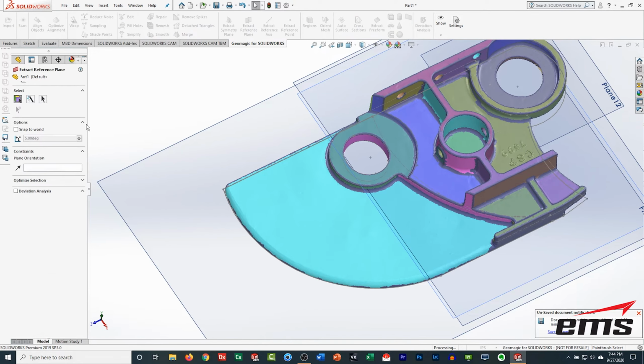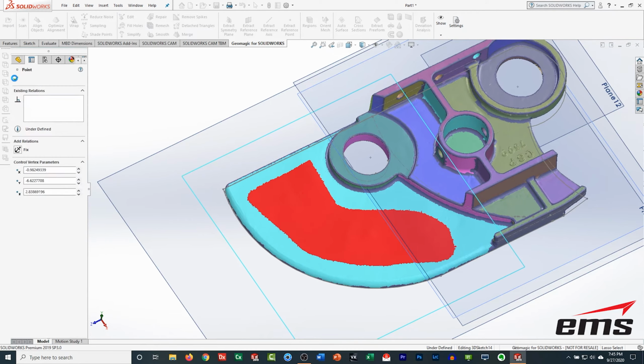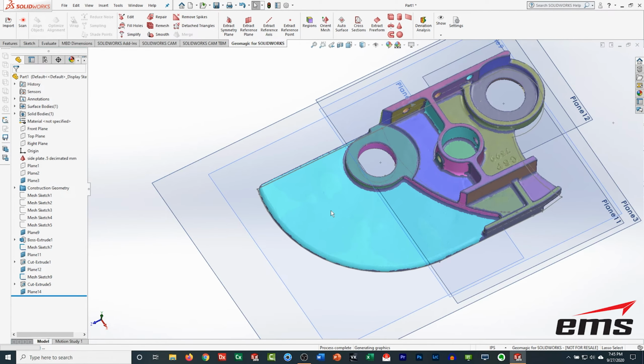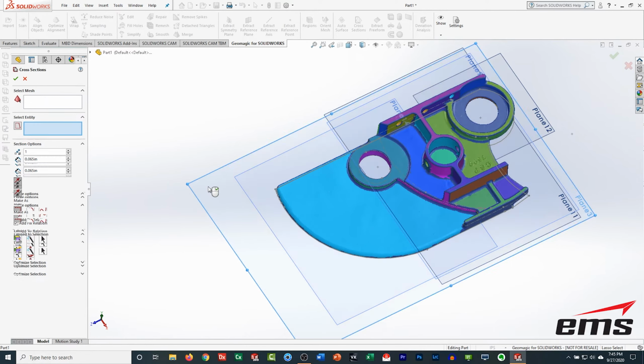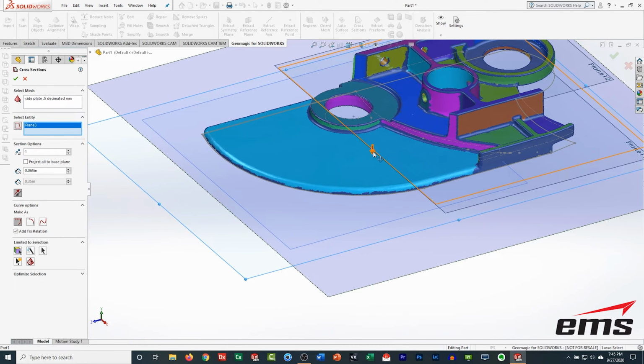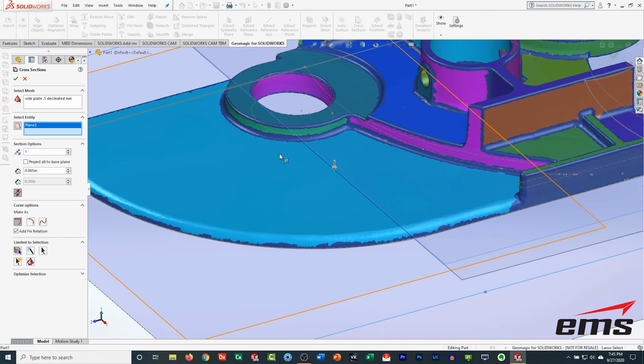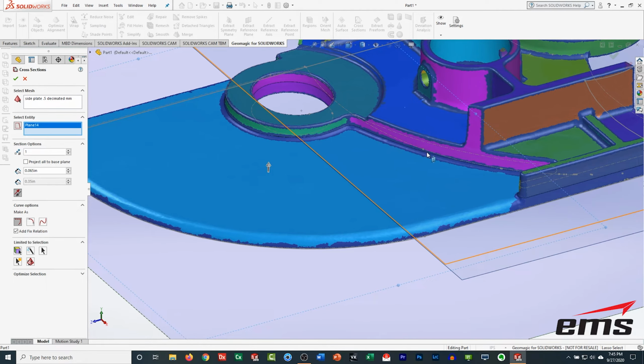Now, you notice this region group curls over that edge. So in this case, I'm just going to manually draw an area and extract a plane. You don't have to use region groups. You can pick points or just use the lasso tool, select some scan data, and fit a plane through that. So that's what we did there.